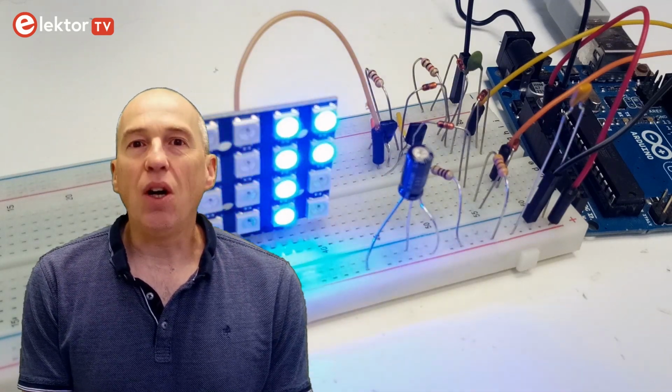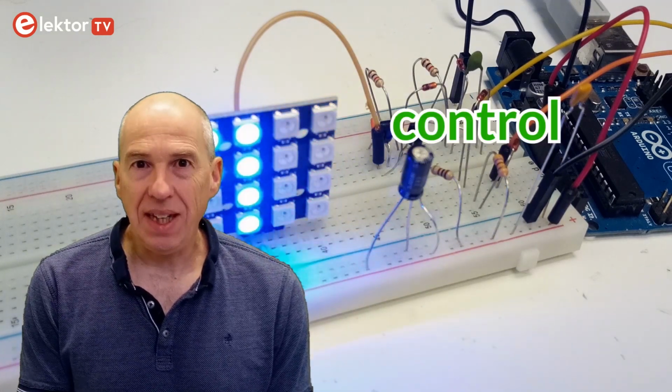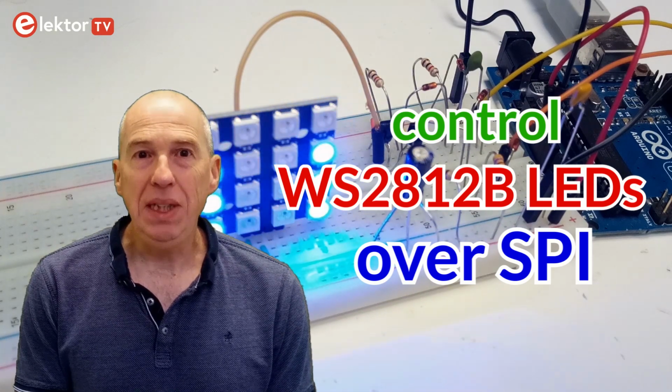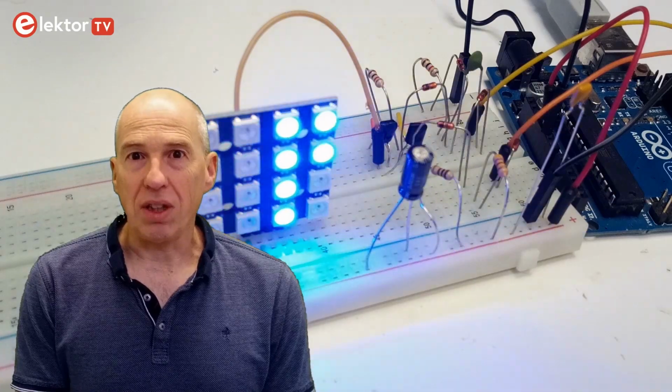In this video I will present some small circuits capable of converting a SPI data stream into something compatible with the WS2812B type addressable RGB LEDs without using a microcontroller.